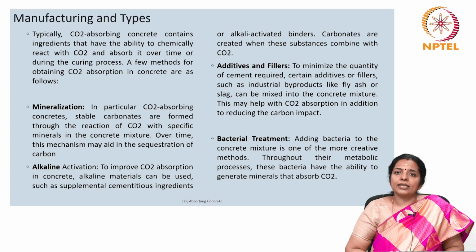There are certain additives and fillers also. Now, in order to minimize the quantity of cement required, certain additives or fillers such as industrial byproducts like fly ash or slag can be mixed into the concrete mixture. This could help with carbon dioxide absorption along with reducing the carbon impact.